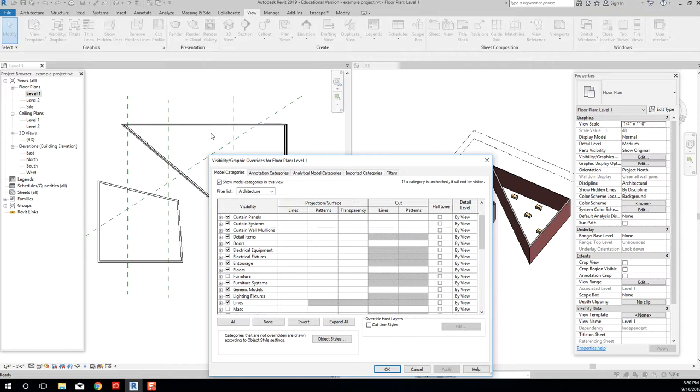Yep. Oh, you're right. Kind of answered my question. I was asked, because you said everything you do happens in all of them, but I noticed in 3D you still see your... Right. Well, and it's because I control the visual graphic. I didn't delete them, right? Pick which view you control. Exactly. Yep. So if I had deleted those desks, though, I picked it and hit delete, it would have gotten rid of them in both views because the model element was deleted, right? But with this visual graphics, I'm just controlling what I see in a view, right? Does that make sense? Yeah, so I'm turning things on and off visually.